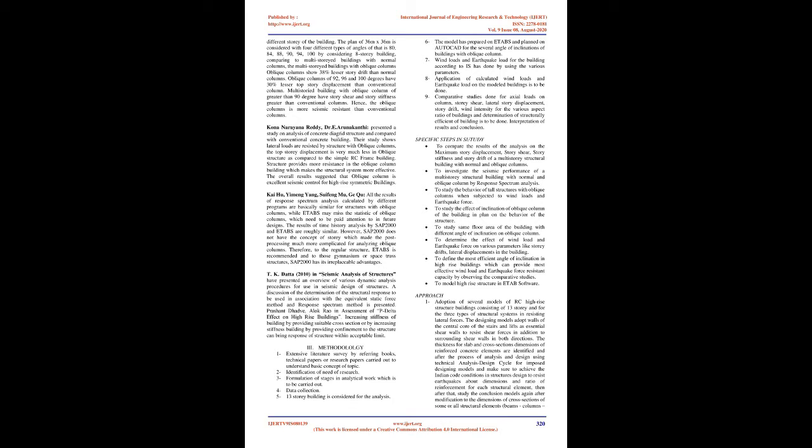It is also likely that a structure may not be subjected to severe earthquake forces during its design lifetime. Reinforced concrete multi-storied buildings, RCMS, are supposed to be of engineered construction in the sense that they might have been analyzed and designed to meet the provisions of the relevant codes of practice and building bylaws. The construction might have been supervised by trained persons. In such cases, even if earthquake forces have not been considered precisely, the structures would have adequate inbuilt strength and ductility to withstand some level of earthquake intensity.